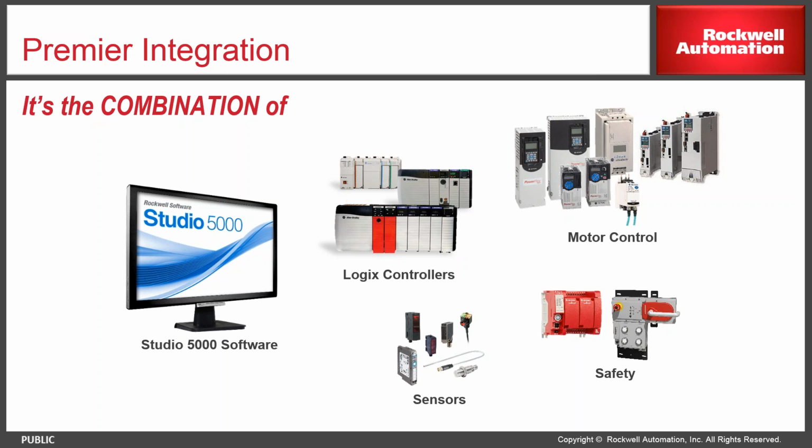So whenever there is a fault in any of the field devices, when they replace it with the new product, they would have to do the teaching of that new product. But with the functionality of automatic device replacement, the teachings are automatically transferred from the PLC, the controller, to the device. So this can save a lot of time. Then it can help in the predictive maintenance.